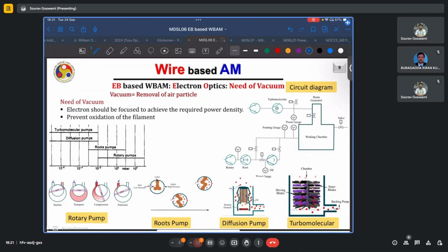Another reason is that for thermionic guns specifically, the emitter is subjected to very large temperatures. And as we know, with increase in temperature, the tendency for corrosion shoots up drastically. So, to protect our emitter surface and to elongate the gun's life, we should maintain vacuum so that the chances of corrosion are minimized to the extent possible.